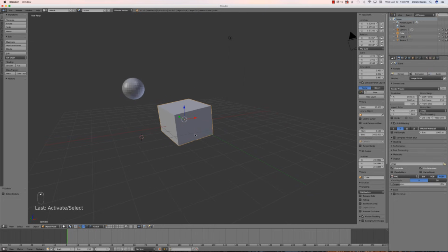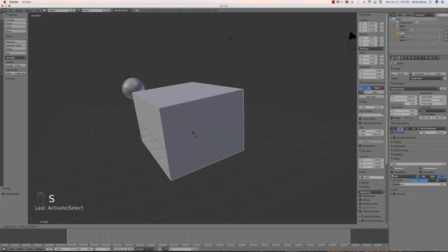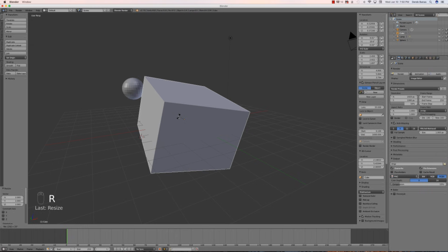There are shortcuts you could use. So I want to do a scale, so I'm going to say S, and I'm going to go 2, and there you go. It automatically doubled in size. And like I said previously, with G, you're going to be able to move it a certain number of units. If you want to set this, just press the left mouse button, and everything goes back. And if you would like to rotate it, let's say 20 degrees, it's selected, you're going to press R and 20 degrees. See, tons of little neat things you can do with this.